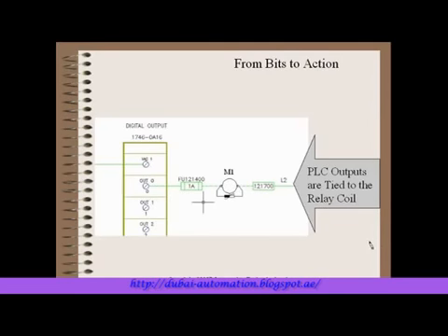Likewise, on the other side, we have our PLC outputs, which is a different type of card that interfaces directly to our relay, motor contactor M1. You see it has a surge suppression device around it to protect the PLC output. Also a fuse, it protects the output. But generally, the main thing you have here is an output directly from the PLC that goes to a relay coil to be able to operate some kind of real-world device.